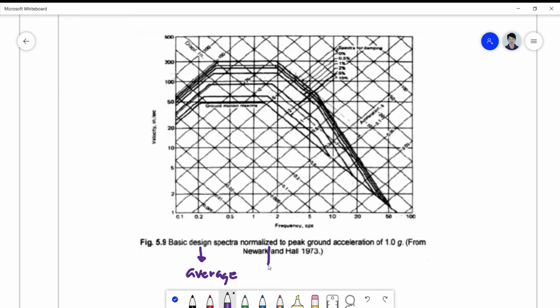Normally, pag sinabing normalize, it's measured in terms of 1 unity, 1 times the gravitational acceleration. Okay? So, if you get a 0.1, you have to multiply it by the gravitational acceleration because your point of reference for acceleration on earthquake is actually the gravitational acceleration.